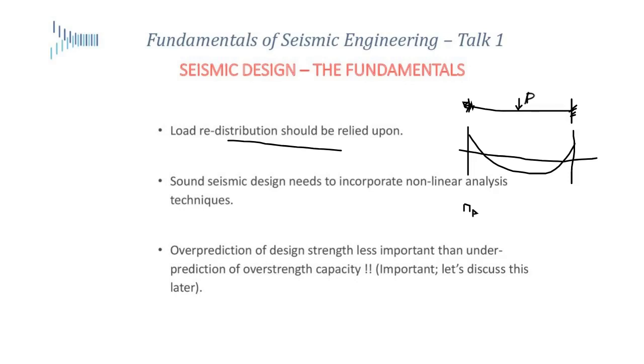Then I could increase the load even further, and this side could hinge. And I could have another plastic moment. Now this beam turns into a simply supported beam. But you see, this thing is still not going to fall if my plastic moment can be locked in here and I can have some ductility. If these local areas can rotate, then what I need to do is form another hinge in the middle here to make this a mechanism. And until it becomes a mechanism, my structure is safe as long as I have this MP locked in and the thing is able to rotate.